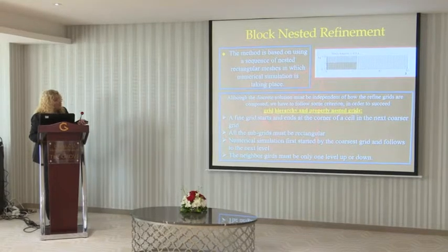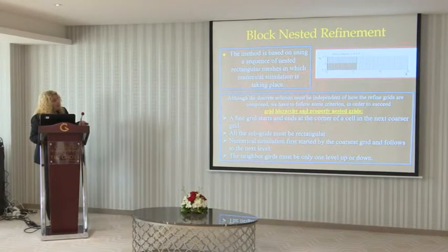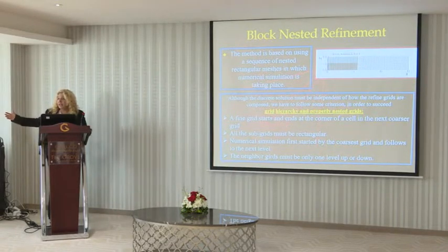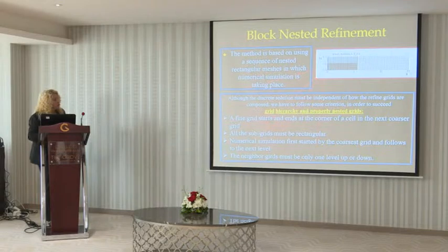So you will see more examples, but you can see a straight pipe that finally will be created like that. If we have these two areas of interest, we are able to refine, while we can create only a coarse grid in order to solve our equations at the rest of the length, which is not so important.